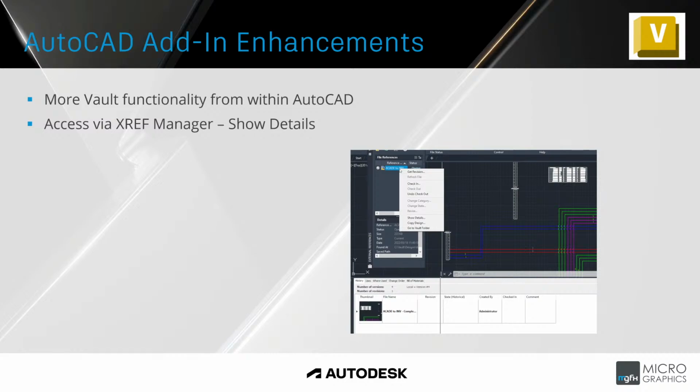all the components that you've put in with AutoCAD Electrical. So all your pilot lights, your switches, your contacts, relays, it'll actually create an item and a bill of materials of that inside Inventor of each component. So you can go into Vault, or even over here, go into the bill of materials at the bottom and see all the components that you have in here, a complete bill of materials, which I think is fantastic. This works really well with Vault, this AutoCAD Electrical.